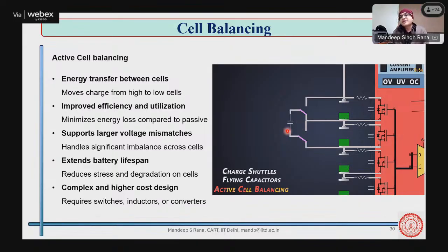Moreover, such a circuit would be needed near each adjacent battery. For example, one such circuit with one capacitor and a full bridge is sitting between the top battery and the second battery. Another would be sitting between the second battery and the third battery. The next will be sitting between the third and fourth battery, something like that. So each individual two-battery pair requires a dedicated flying capacitor.